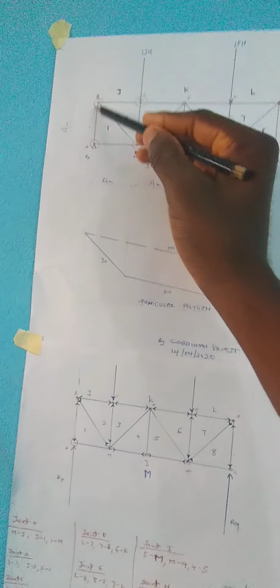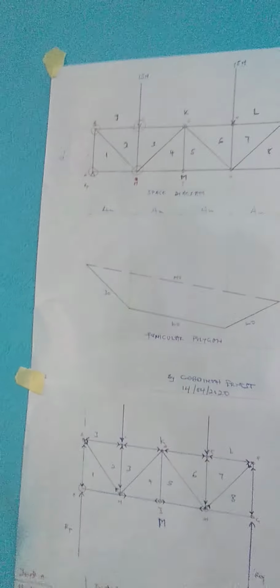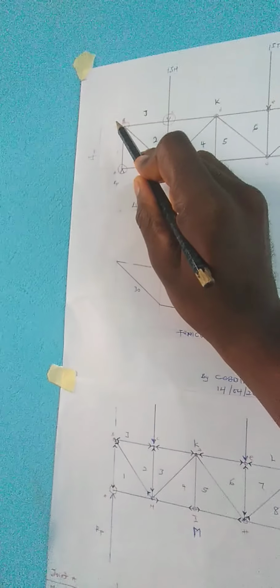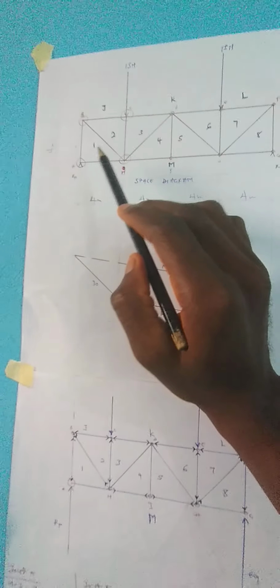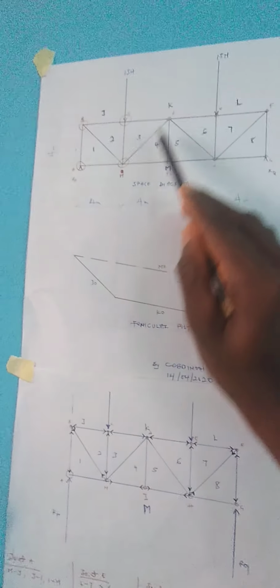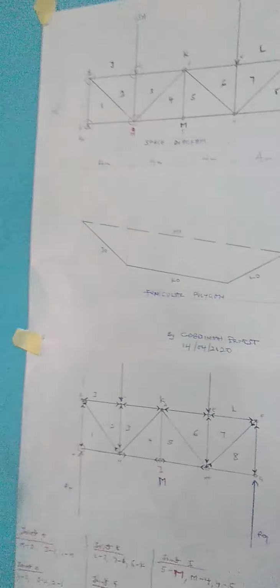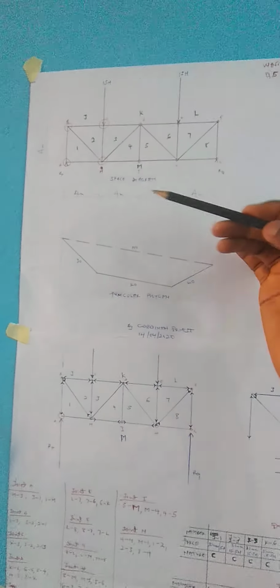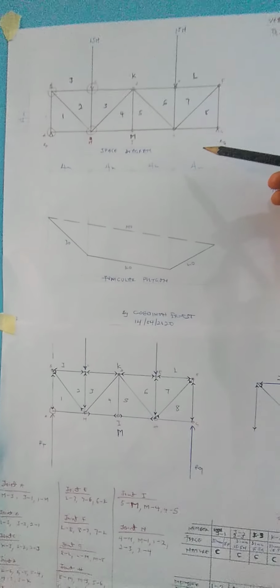When you move to the vertical height, the dimension there was 4 meters as well. So you convert that 4 meters also into millimeters so that it can be drawn. And that one will also be 40 millimeters. When you are done, you join the diagonals. So I do believe that the construction of the space diagram will not be anything difficult to go by. Now, we're done with the construction of the space diagram.